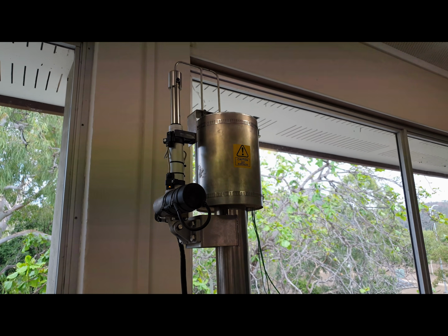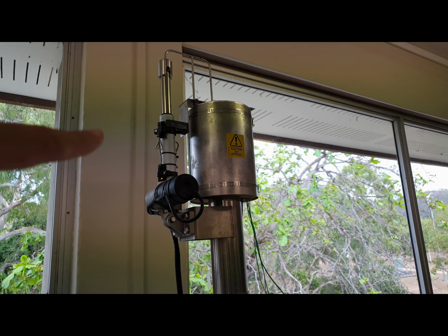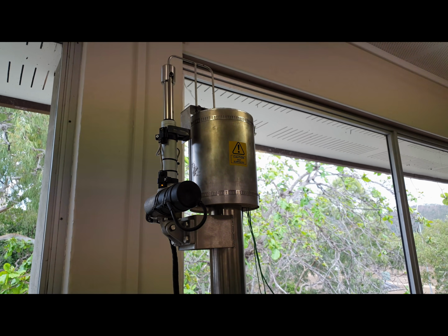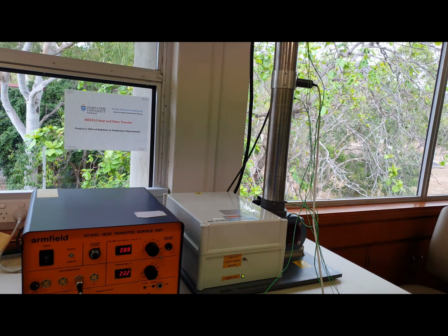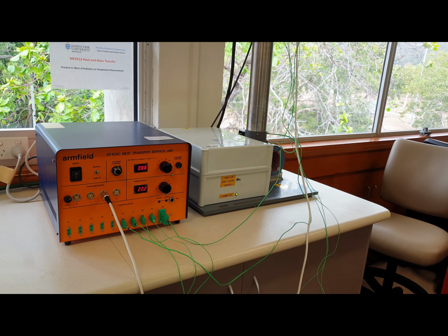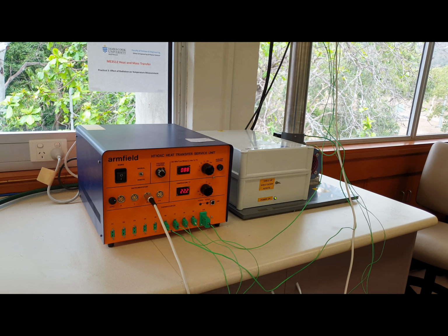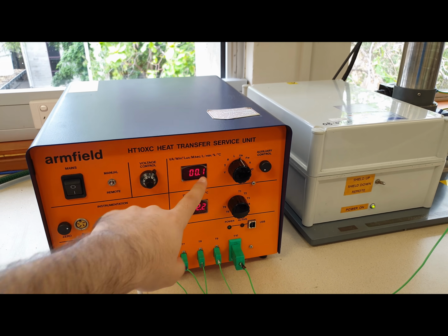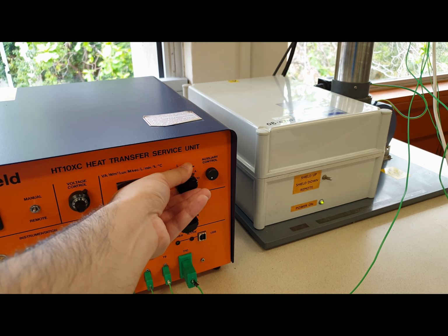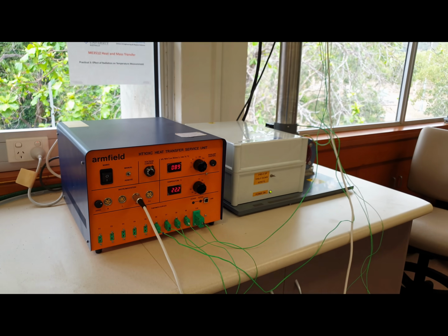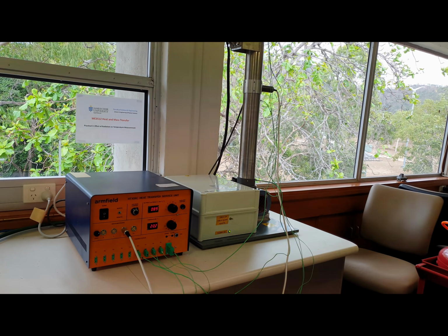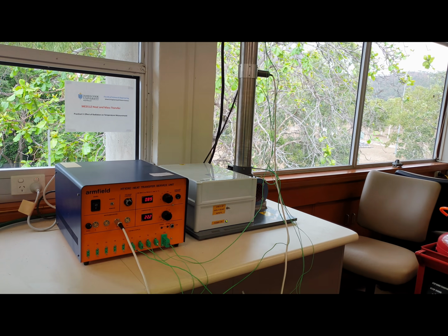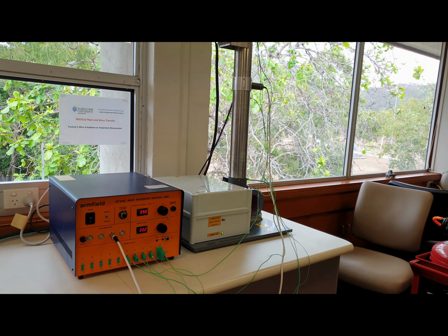As you can see, this jack raised our radiation shield inside the cover, and we are going to have radiation over our thermocouples and no forced convection. To check that, we can check the velocity. As you can see, it's almost 0, so no velocity. Now again, for this case, which is having radiation but no forced convection, we are going to wait to reach a steady state and read all those temperatures.